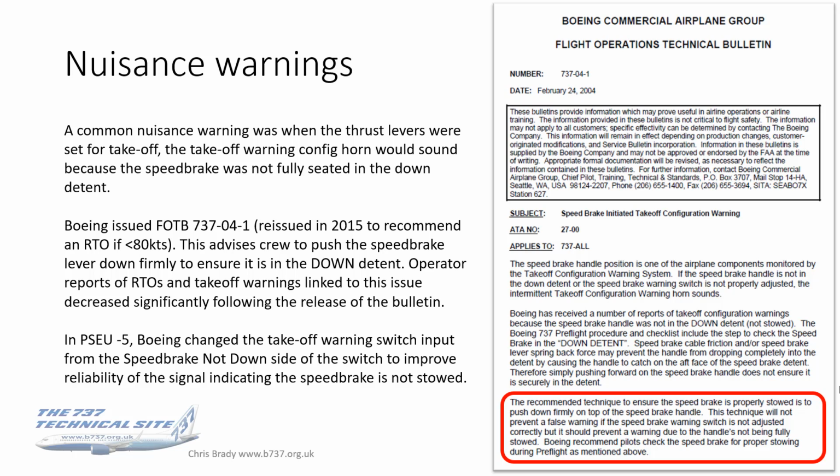PSEU Model 5, Boeing actually changed the takeoff warning switch input from the Speedbrake not-down side of the switch to improve the reliability of the signal indicating that the Speedbrake isn't stowed. So again, these things all gradually get ironed out with time.